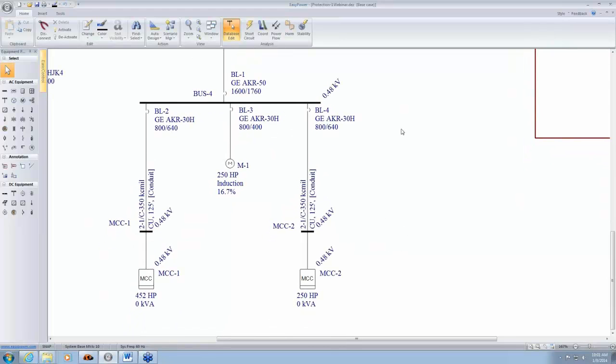First of all, we're going to talk about time current curves. There are many forms of doing selective coordination, and one of the most popular ones that is used in distribution systems is coordination of time delays and pickup settings for the purpose of having a well-coordinated system.